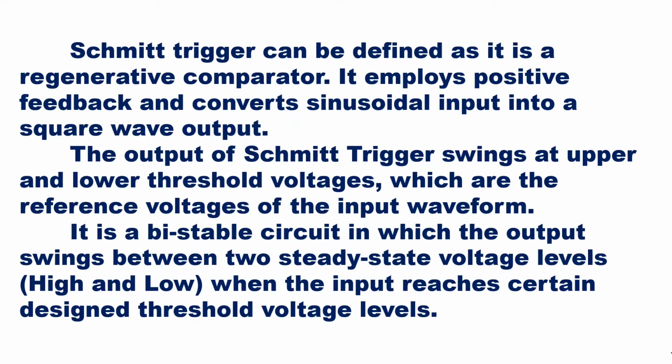Now, if you go to see the basic definition of Schmitt Trigger, it is a regenerative comparator circuit. That means it is going to compare two inputs. One of them will be a sine wave input, and the other one will be a reference voltage, which will be derived from the output of the same circuit.